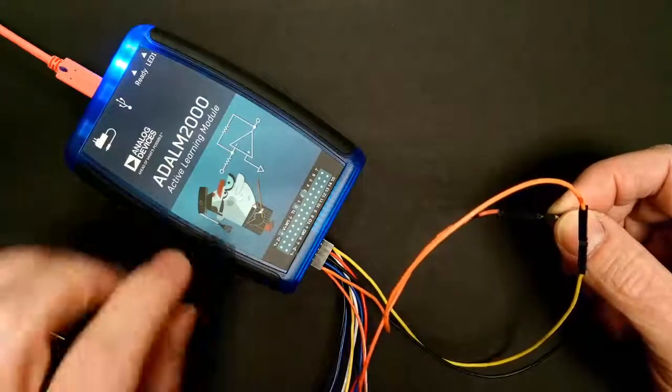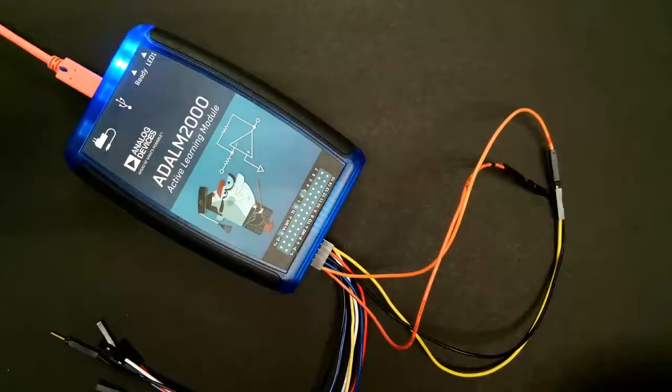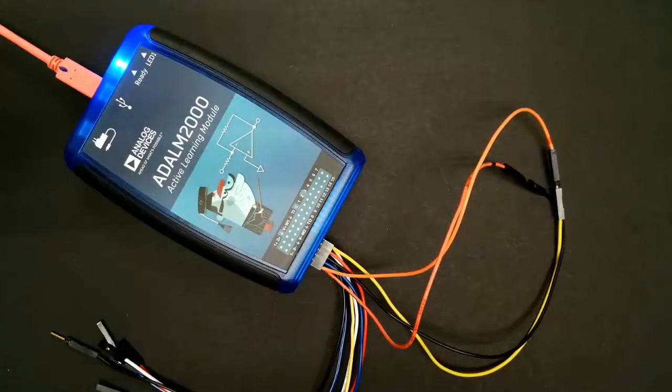So this other lead on the oscilloscope, which would be labeled 1 negative, is not actually connected to ground. And that's one of the differences from a benchtop oscilloscope. When you use a benchtop oscilloscope with a BNC connector, that metal portion of the connector, the outer shell, is always attached to ground, where in this case it is not. It's a floating measurement, and you can use that as a good tool for certain experiments.